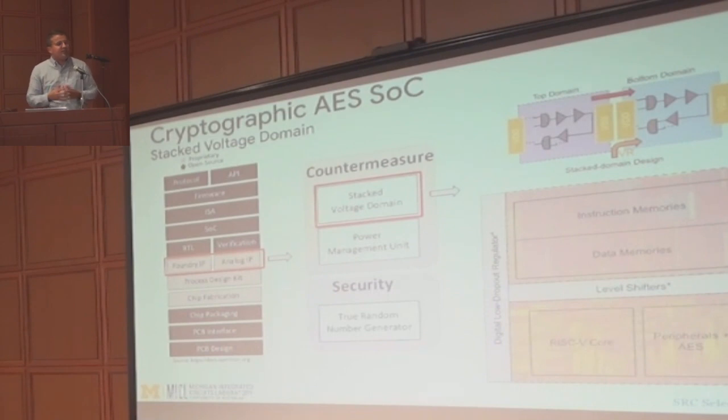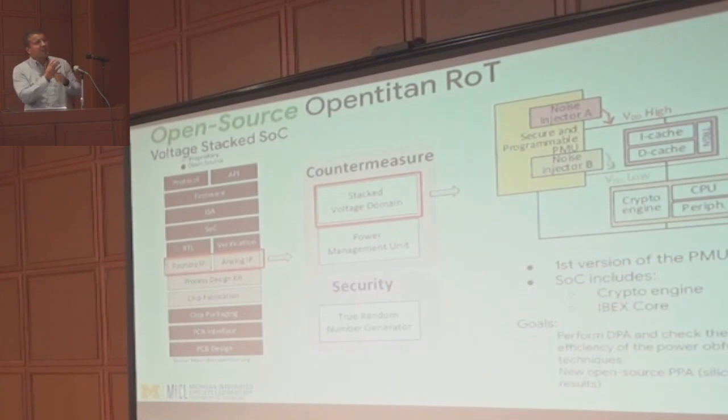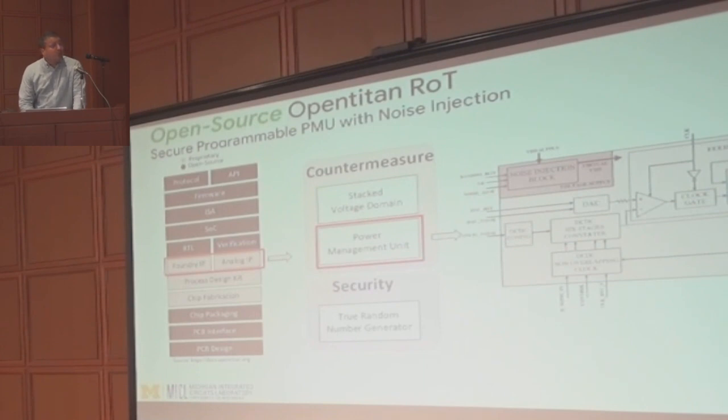We actually did an experiment here. We already created the stacked voltage domain, so there are two voltage domains on top of each other, and the lower voltage domain is using glue logic, so the accelerator is sitting there and it can run at subthreshold voltage. I'm going to show it here, and we included noise injection in these blocks, and the higher voltage domain has all the analog blocks like the PMU and the memory caches, which are not very amenable to scaling the voltage.